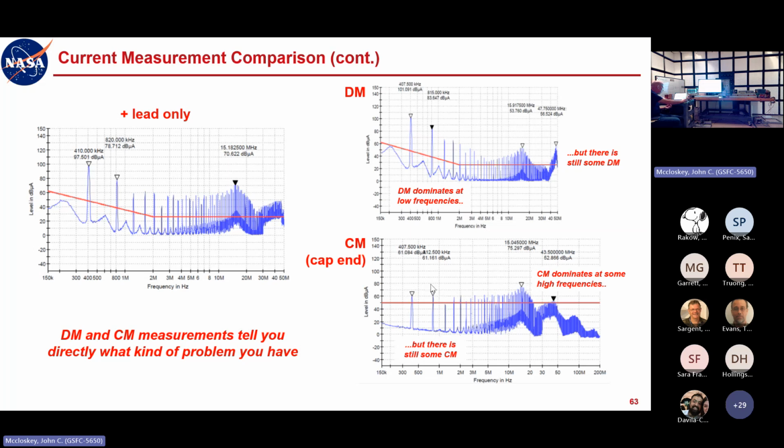So here for common mode, you're maybe 5-6 dB above the limit. You still need some common mode filtering at low frequencies, but you need a lot more filtering for differential mode at those frequencies. Because here, that's 20 dB per mark there. So you're like 50 dB above the limit down here. So this tells you, all right, I can't neglect common mode. I need some common mode filtering, but I need a lot of differential mode filtering.